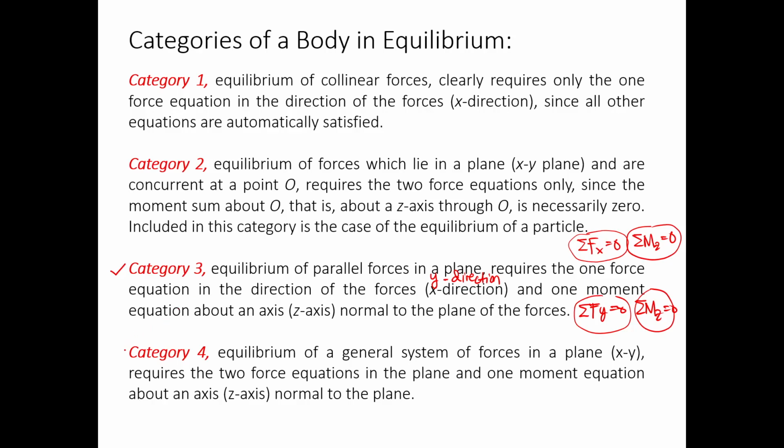Now for category 4, which is on Thursday, this is the general system of forces or the non-concurrent forces. This will require us to use the two directional force equations, x and y, and then one moment equation about an axis. It could be the y-axis or the x-axis depending on the problem.